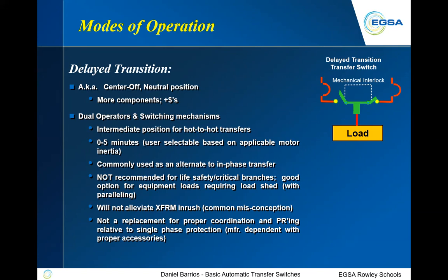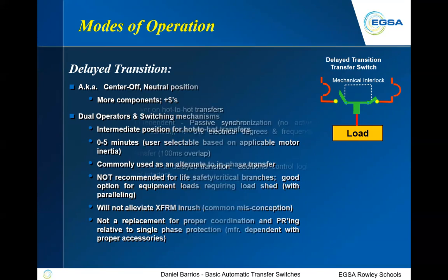And this is not any type of replacement for any of the other inputs. It will not alleviate transformer inrush. Transformer inrush will happen when you re-energize. However, all transfer switches are aware of that. They will ride through that momentary surge of power while that transformer is taking a few cycles to be re-energized.